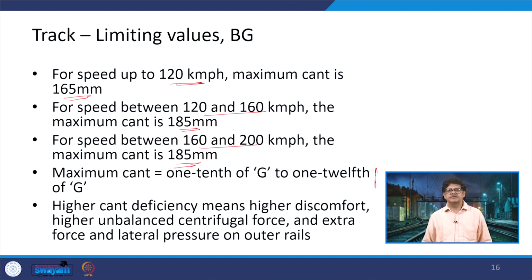Now, higher Cant deficiency means higher discomfort, higher unbalanced centrifugal force and extra force and lateral pressure on the outer rails. I think there is no need to elaborate on this particular point, because we have already discussed Cant deficiency and the way it is going to impact.